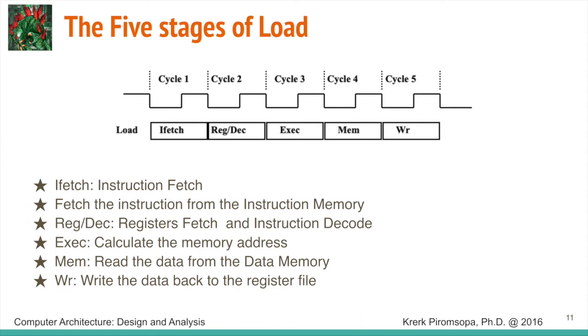Now for our processor, to have a pipeline, it just fits nicely with our 5 stages. So these are the 5 stages of the load instruction. You got fetch, decode, execute, mem access, and write back. It just happened that these are also the 5 stages of our pipeline because it kind of fits nicely.